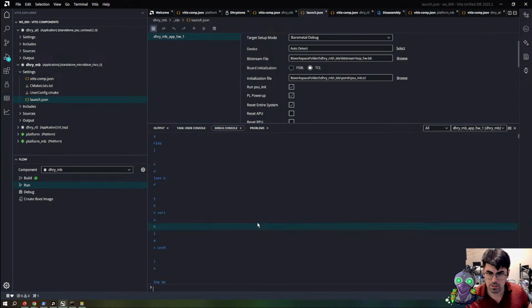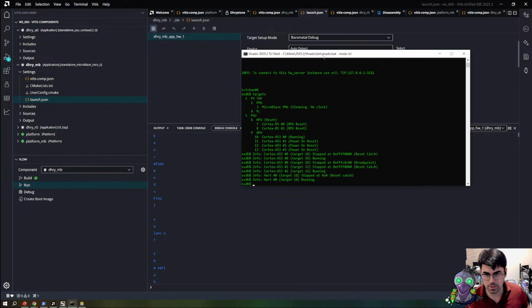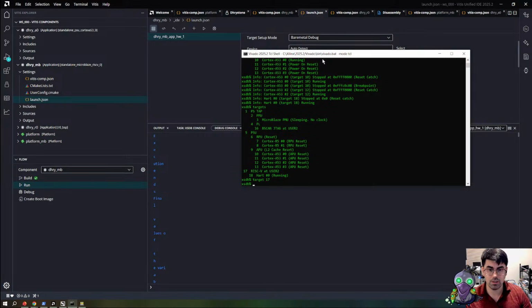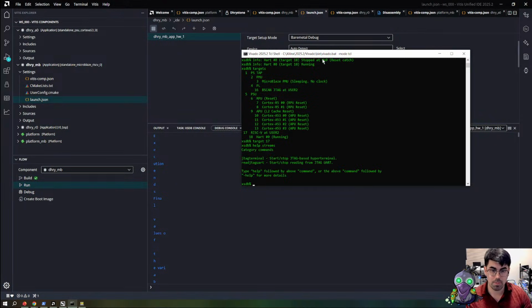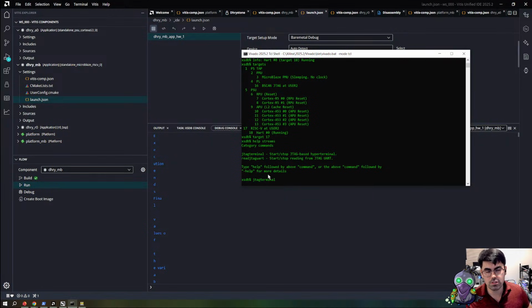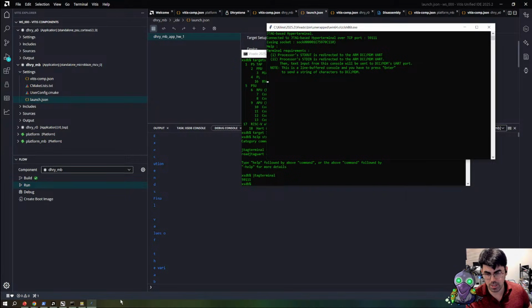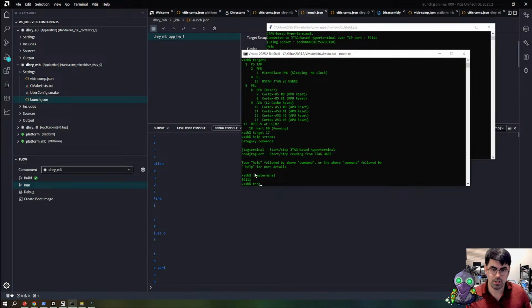Okay, so we had the UART here. The MicroBlaze-V has a little issues with this, so let's look at it in a better format. I'll show you how to set this up. We go to targets, we go to target 17 right there, and we go to hw streams. Target 17 is the RISC-V at user 2, which is a B-scan. We can start a JTAG terminal at target 17. So we just do JTAG terminal, and this is going to open up an additional window where we have dedicated communication.